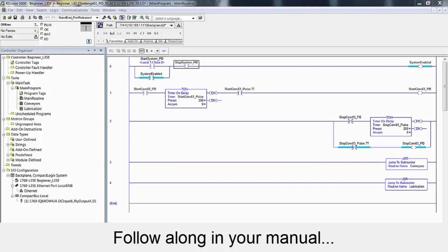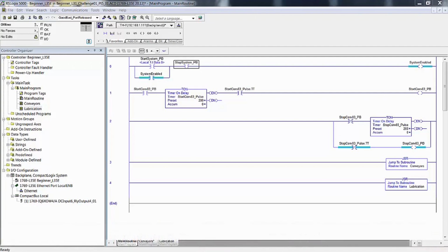Each conveyor has an entrance photo eye, the location of which assumes that when a carton comes to rest against the leading edge of that conveyor belt, the carton is blocking, sensed by the photo eye at the entrance of that conveyor. Meaning that if a carton comes up to conveyor 1, even if conveyor 1 is not running, the leading edge of that carton is far enough into the beam of 1 PE that it is blocked, so 1 PE or local 1 I data 1 knows that there's an object there.